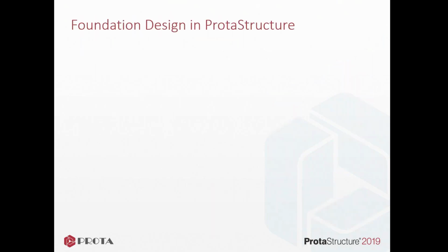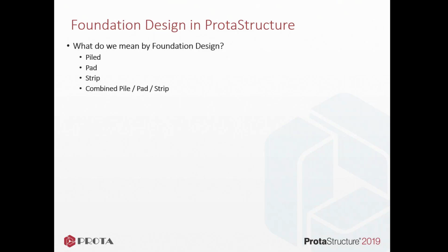So for our foundations in ProtaStructure, what do we mean by foundation design? Well, in Prota, we're covering a really broad range of different foundation systems. So these can be pile caps, pad bases. We also support strip footings, combined pile, pad, and strip design. I'm also going to touch today on raft foundations and piled rafts. You can also introduce foundation beams into our systems, and we can also look at unique foundations, especially those where you may have to consider eccentricities.